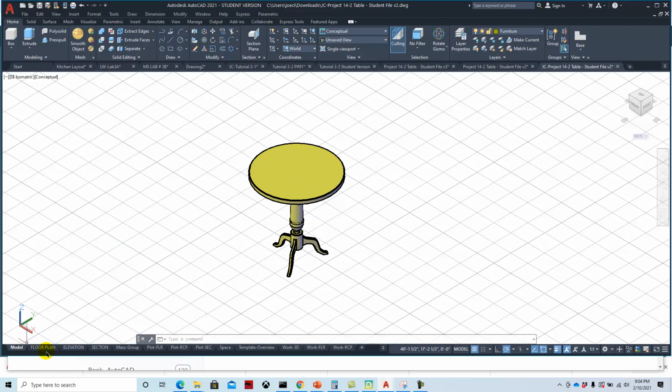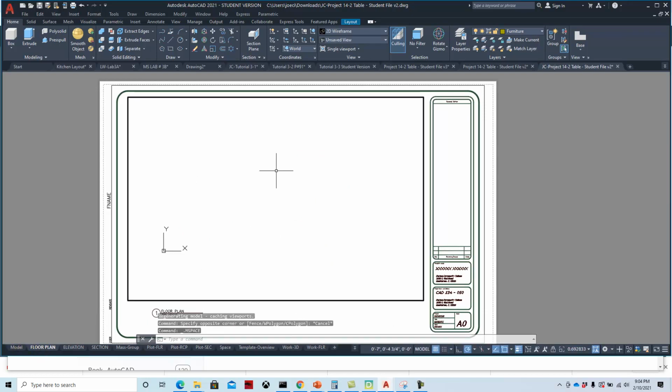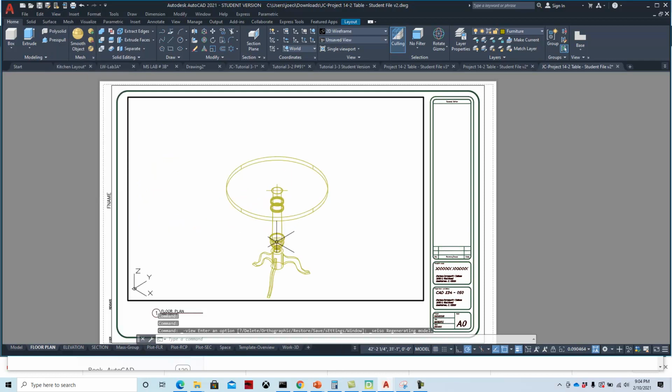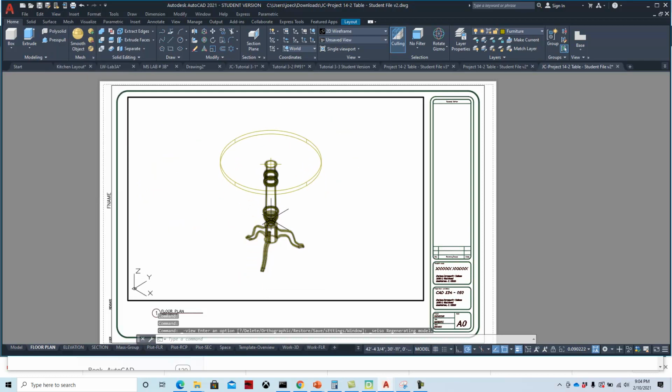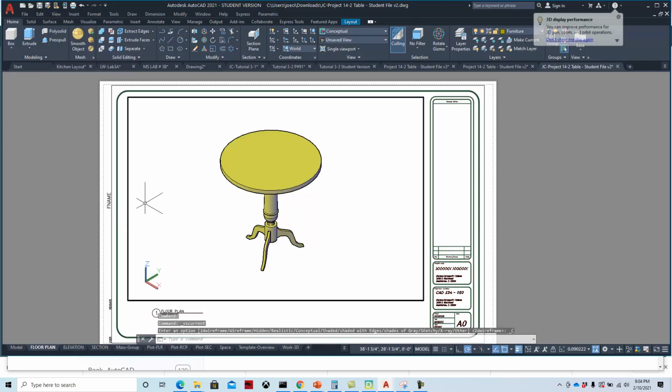I think what I might do is 3D print this. Double click in the viewport in paper space, double click on the mouse, and then we can go through and create the views for this. We'll change that to a southeast isometric. I'm just going to kind of make that by eye. And then I'm going to put a visual style of conceptual.